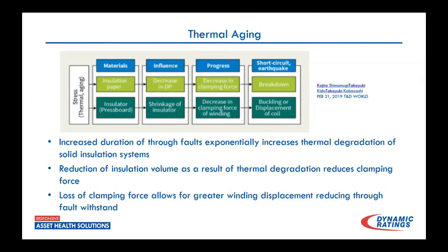And then the other tests that we run in our usual maintenance would be power factor testing. And that's really hard to see movement of that type, because it is a very small grade of movement in the beginning of this problem. I've seen transformers that actually had one that comes to mind right away. I had a low side bushing failure. Went out, we did a power factor test.